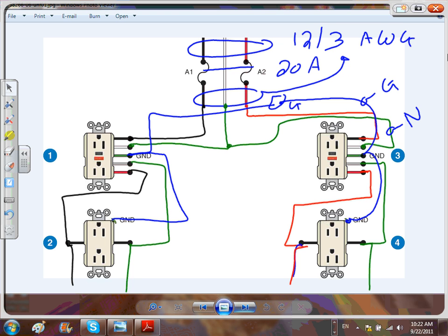Okay, tamper resistance, the one right underneath it. Number 3, tamper resistance. If you change a receptacle in an area that needs tamper resistance, effective now, you have to change it with a tamper resistant receptacle. Weatherproof, right underneath it. That changed in 2011. If you change a receptacle in an area that needs weatherproof, all the receptacles in damp and wet locations, that receptacle that you change, not install, change, replacement, maintenance, has to be weatherproof. Very important. That changed in 2011.